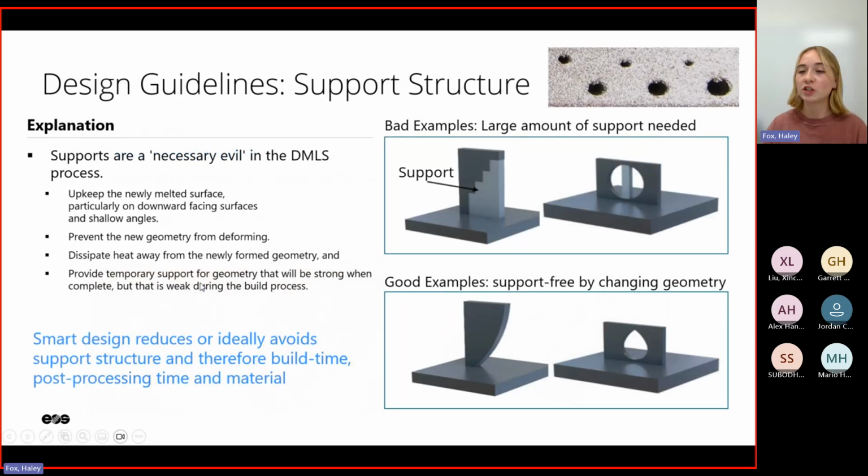All right, so just some more design guidelines. Usually holes are quite an issue when it comes to not only metal powder bed fusion, but also polymers. So you can see here that sometimes in this top right image, you can get away with holes being printed in an XY plane, or kind of horizontal, if you will, printed through. And so at some small hole size, you can get away with no supports inside, but you will always have this kind of divot on the top.